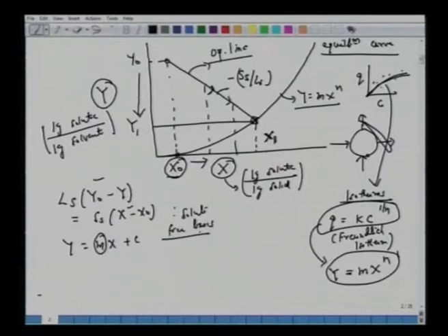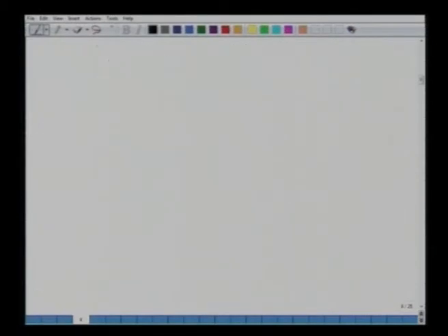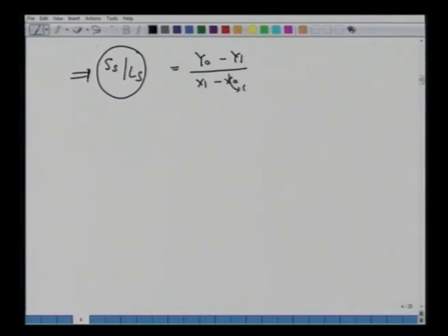All right. So coming back to these equations, now you can write Ss over Ls. So how much amount of charcoal or adsorbent is required per amount of solvent. This is equal to (y0 minus y1) over (x1 minus x0), but let's say x0 is a very small amount, very close to zero, your fresh adsorbent, or this amount is much larger than x0.